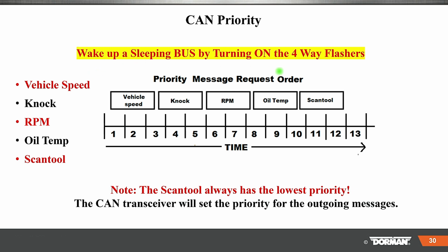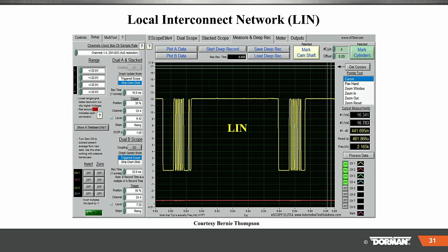To wake a bus up, if you open the door, you're going to see that in a little bit, or if that doesn't work, you put the four-way flashers on. Slide 30, please circle that. Some people don't know that. Slide 30, please circle that. Four-way flashers going on and off will wake the circuit up.